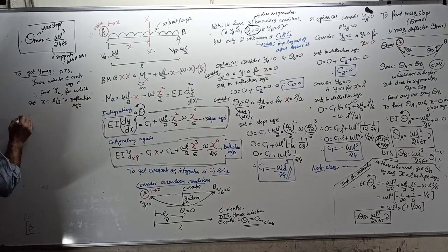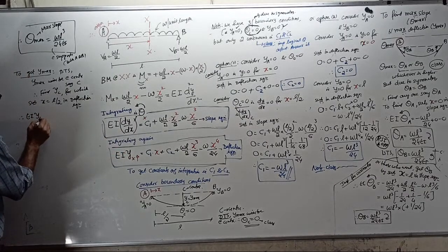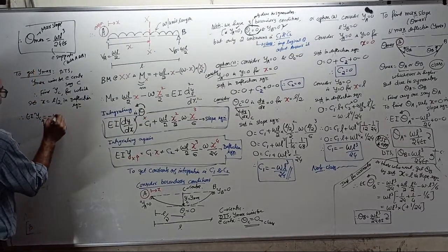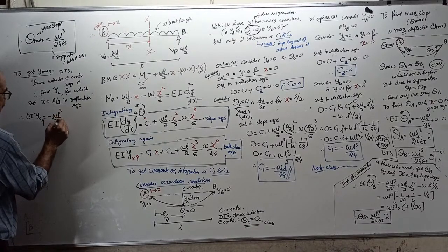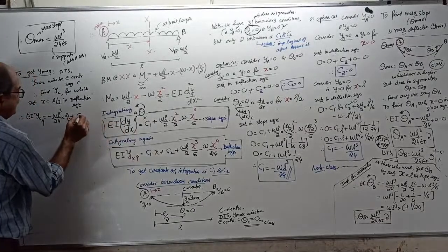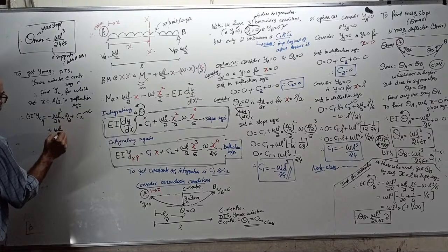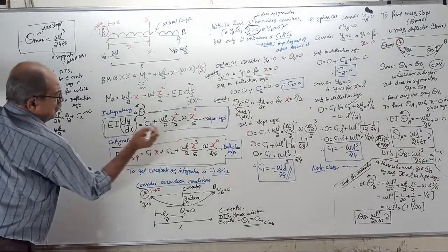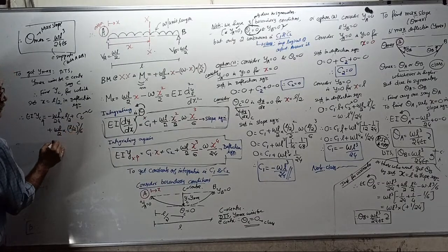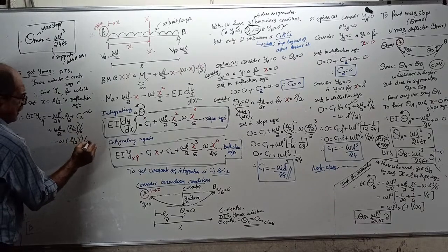Therefore, EI YC, upward positive, equals C1 into X minus WL cube by 24 into L by 2, plus C2 which is already 0, plus WL by 2 into (L by 2) cube divided by 6, minus W into (L by 2) power 4 by 24.